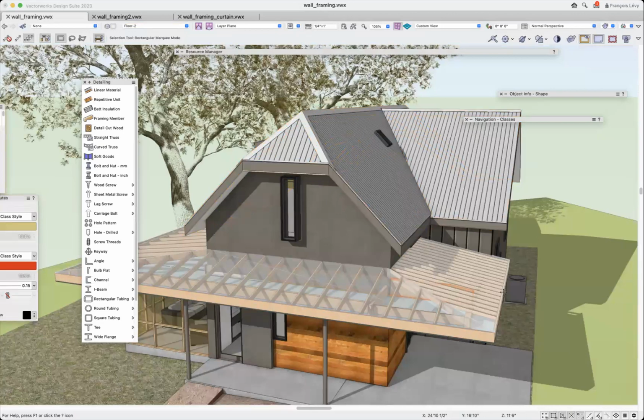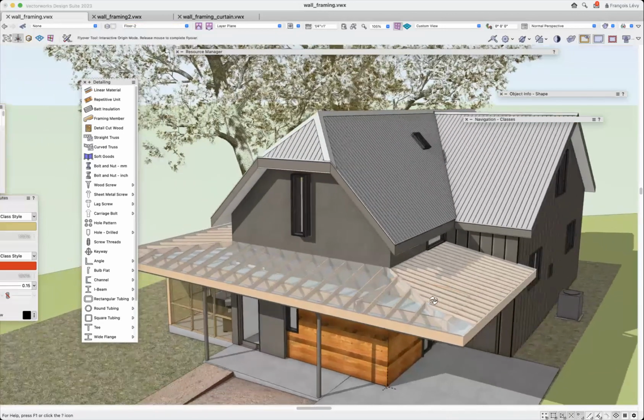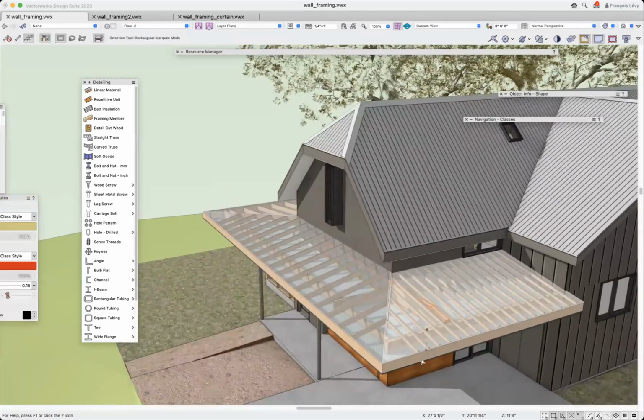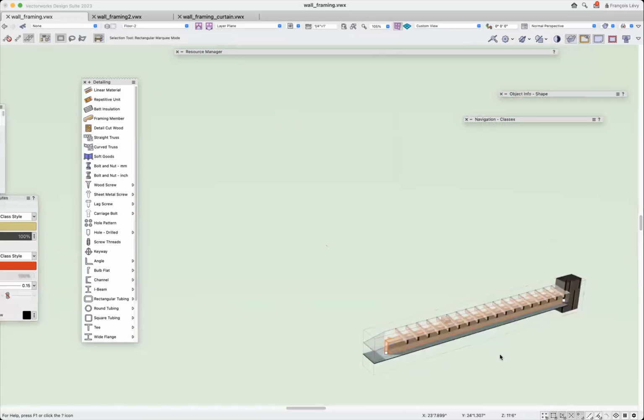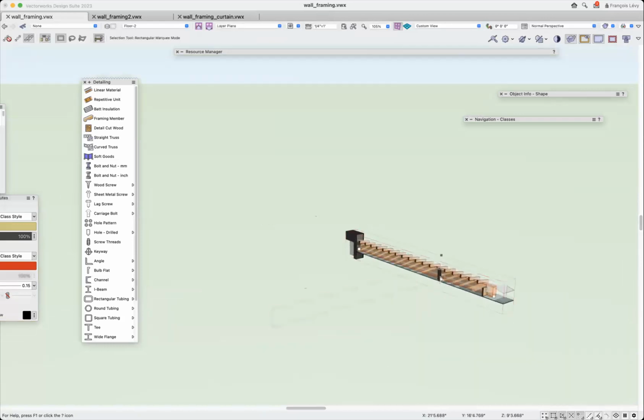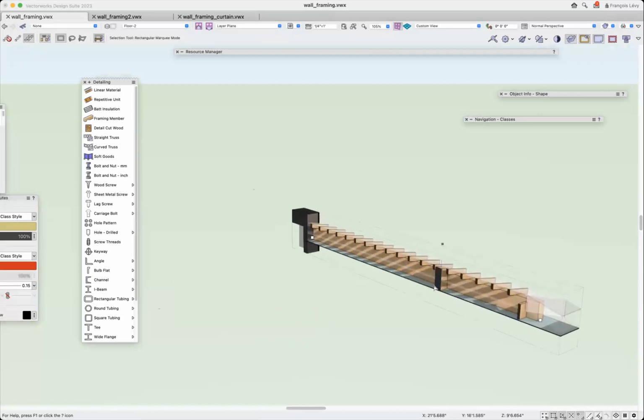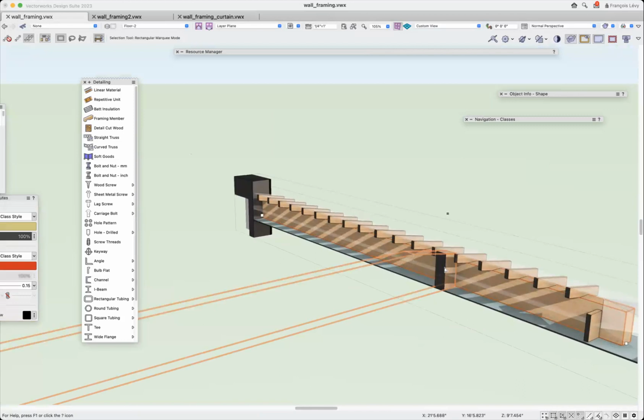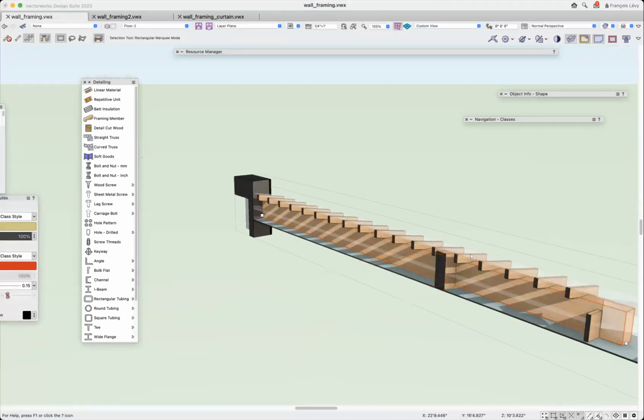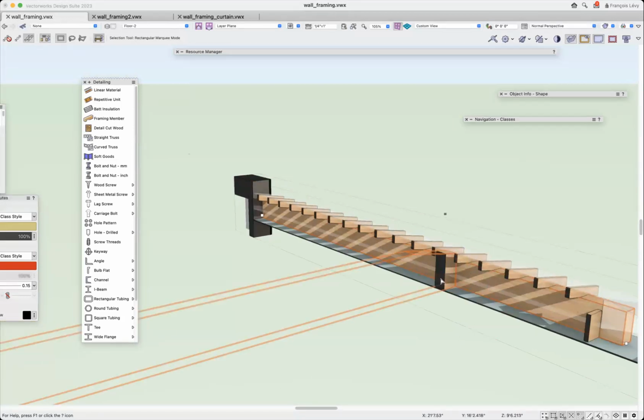So there it is. And then next, there is another beam out here, right? Let me use the clip cube to isolate that. That's just spanning from the corner of the building, so it's supported on the building itself. And then about 2/3 of the way along its length, right over here, you can see where the pre-selection cursor is highlighting the first beam that I just showed you. That beam is carrying this one. And so everything to the right of this beam that I've just selected is a cantilever.